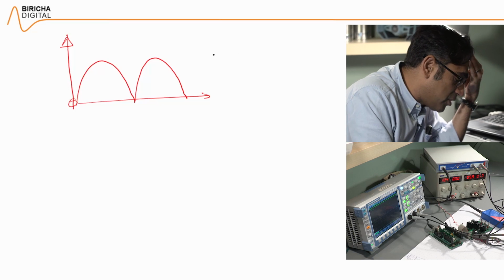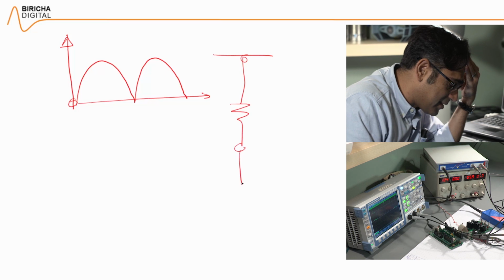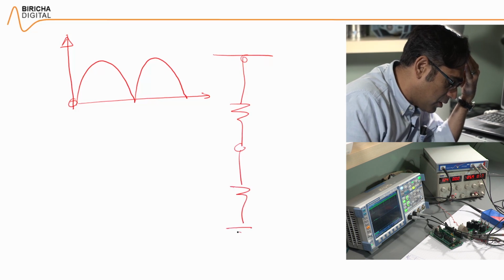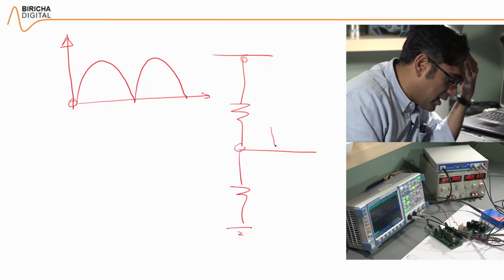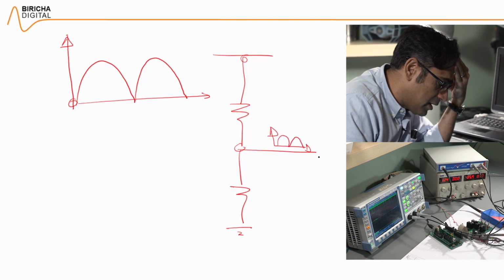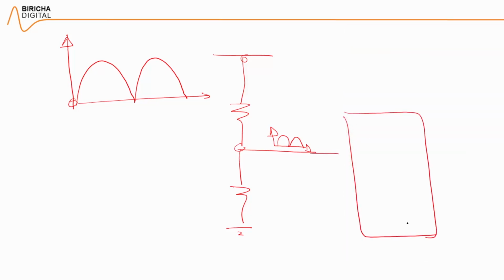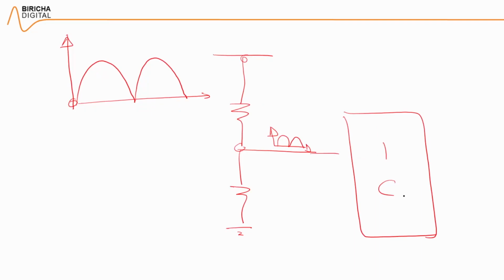And then in analog, because you don't have any mathematical functions or very limited, what you do is you pass this through a potential divider, and this will be the demand value of your current, and that goes into your analog IC.